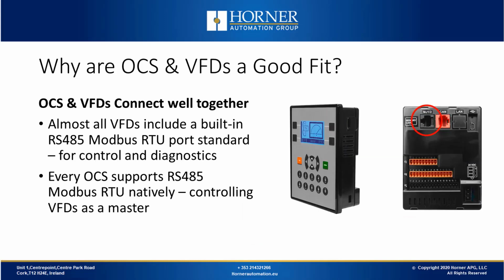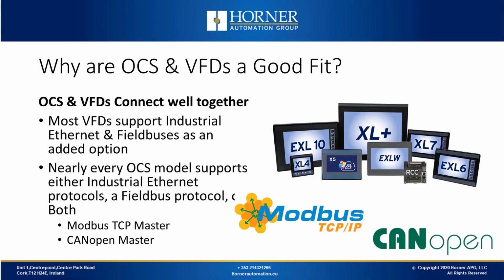You can also control a VFD using RS485 through the Modbus RTU protocol. This feature is standard in every OCS that we sell. We also support some slightly more advanced communication options, including communicating over Ethernet as well as CANopen. There are certainly some advantages to Modbus TCP, and it's a little bit easier to work with than Modbus 485. CANopen has some advantages in terms of communication rate as well as synchronization functions that you won't find with a typical serial communications protocol.